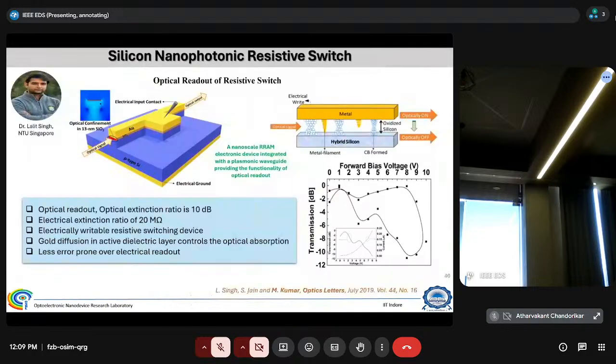So then in our nanophotonics, basically utilizing hybrid plasmonic behavior, what we have here is silicon, and on top of this you have SiO2, thermally oxidized SiO2, and then you have gold. So what happens basically is your light, in the form of light and plasmonic confinement, because of the gold and dielectric presence there, you have a combination of SPP, plasmonic confinement, as well as light.